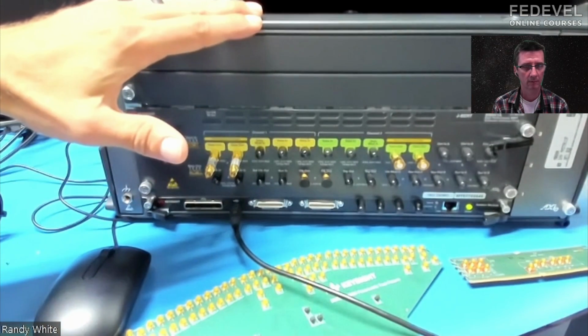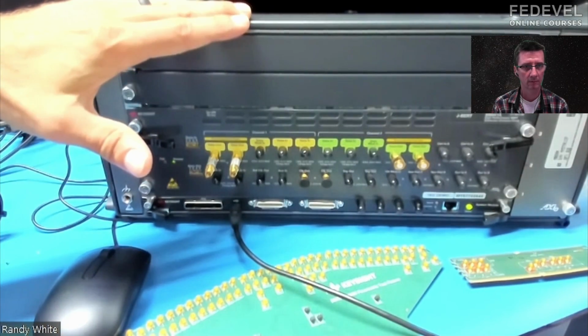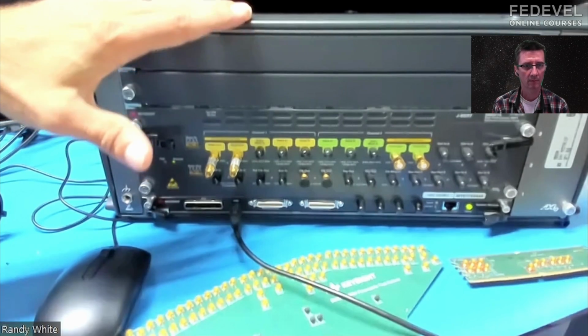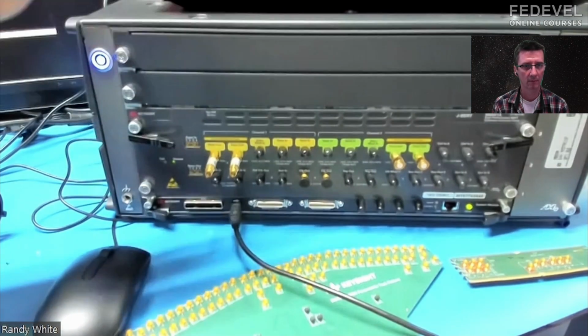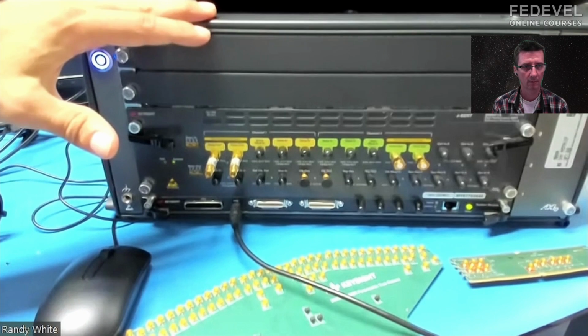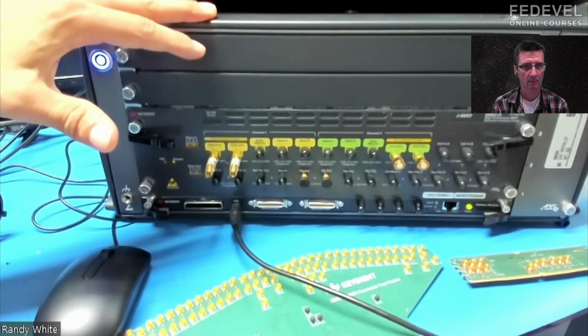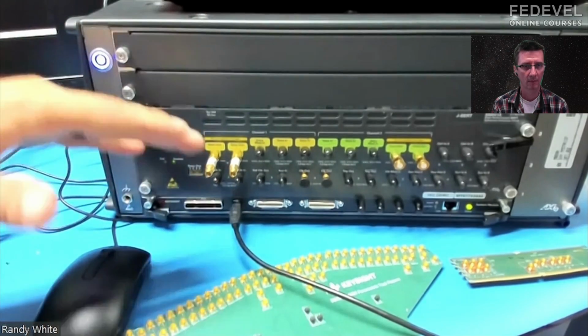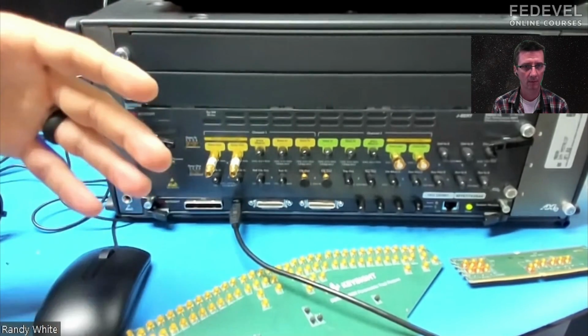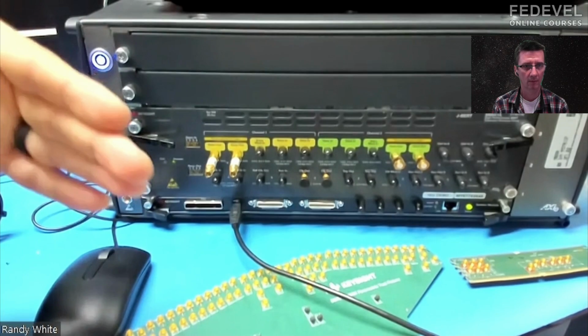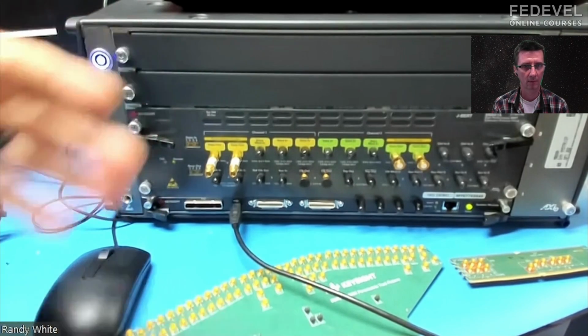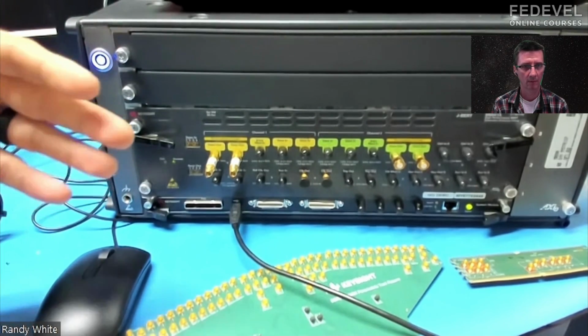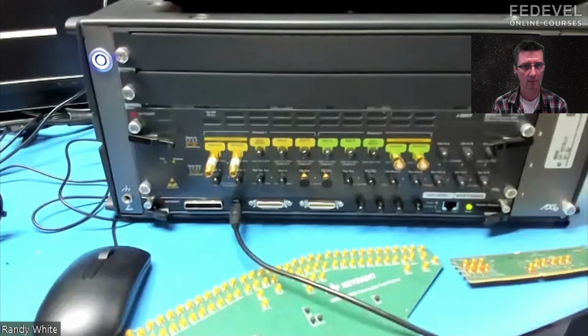This is just testing the DRAM in isolation, right? We want to test the interface. We want to test the physical layer. How good is the transmitter performance of just the DRAM by itself, which is why we have these coaxial connectors, right? Very controlled impedances, clean launch, unlike the soldering probes, which is more system level.